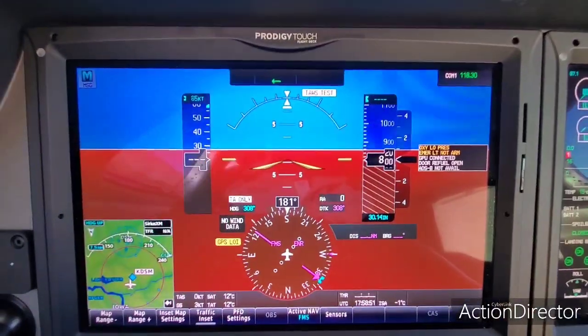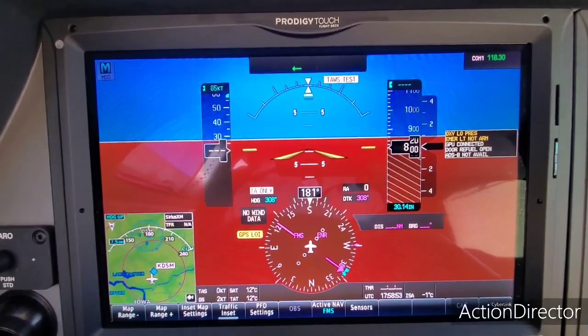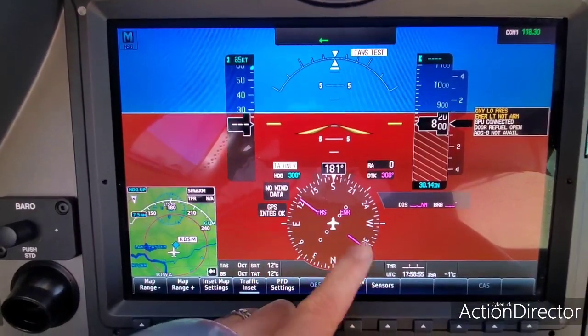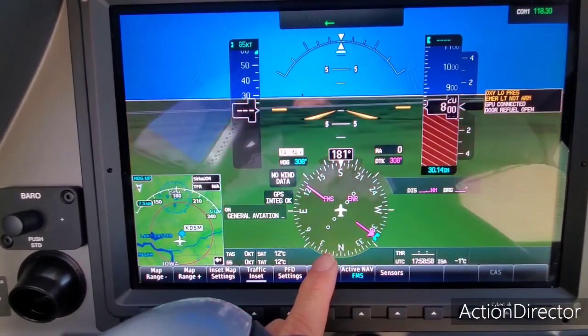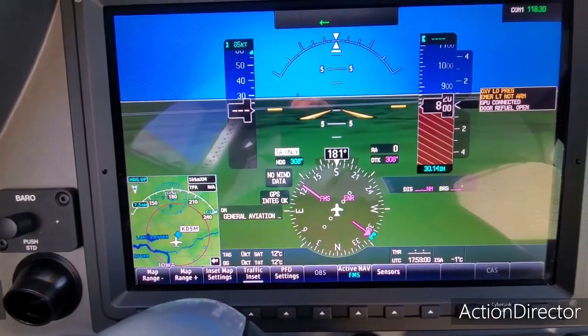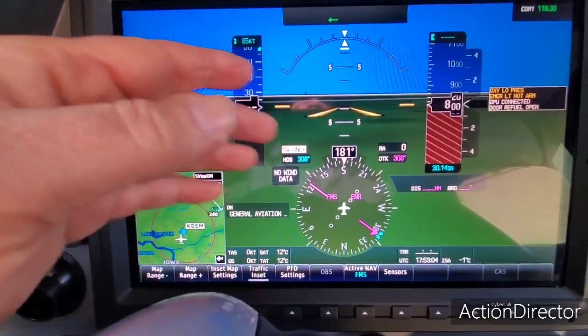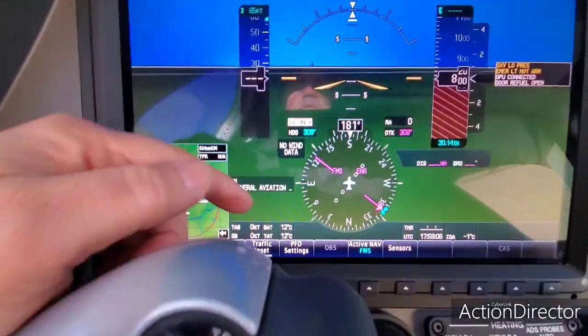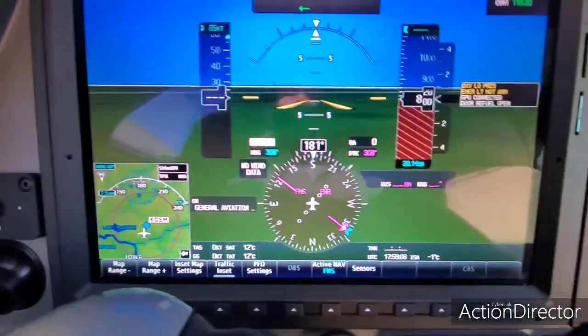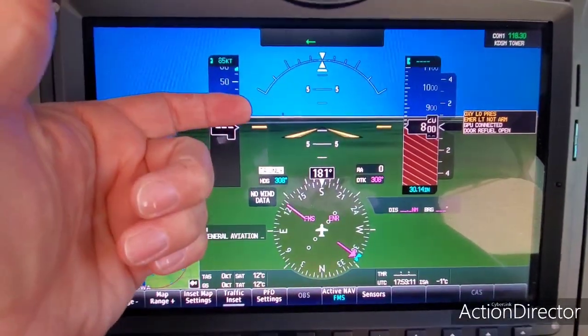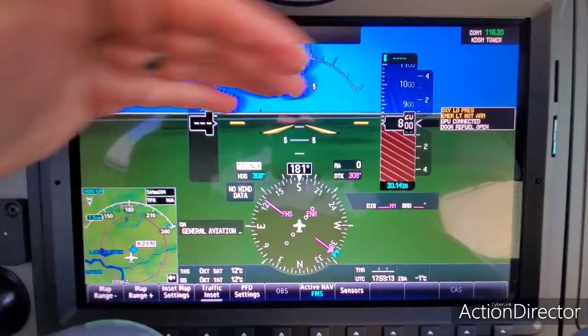Now, if you're used to an old airplane, it's very similar, it's just in a digital layout. Down here, we have the compass. In this case, it's an HSI because there's navigation on it. You just saw that turn green because that's part of the TAWS, or the synthetic vision, so it'll actually show what's out there. You know, like a tower's out there showing the runway. Here's your, we call it an ADI, but that would be an attitude indicator. The old T formation for the old gauges.